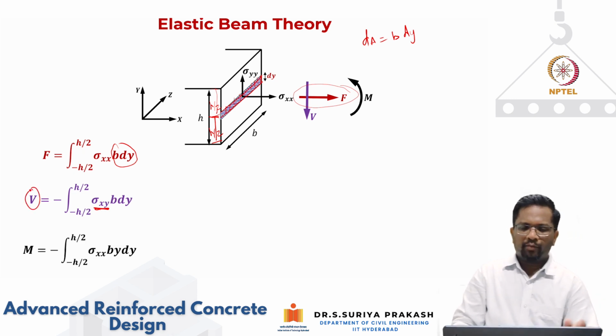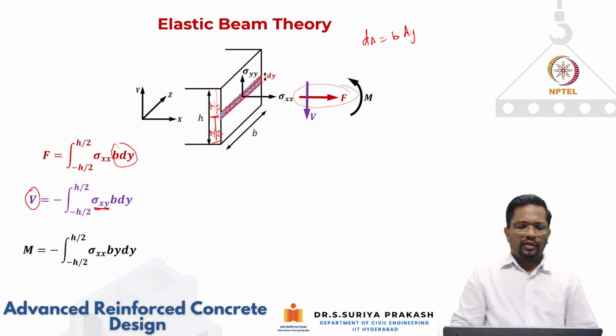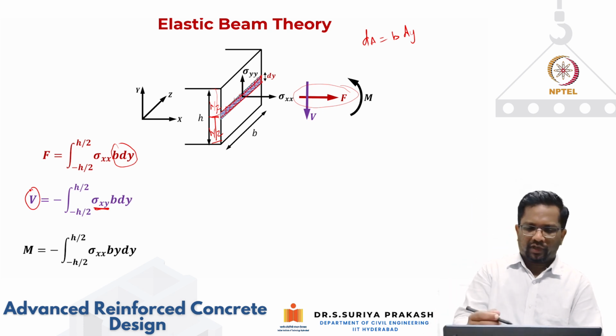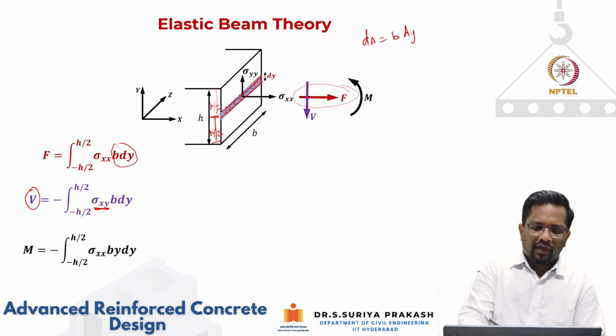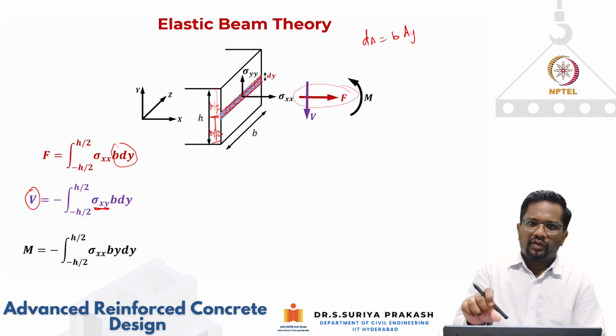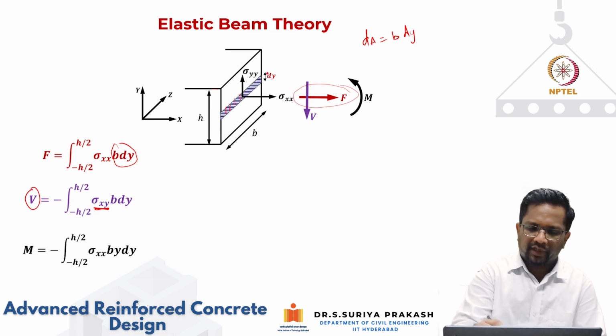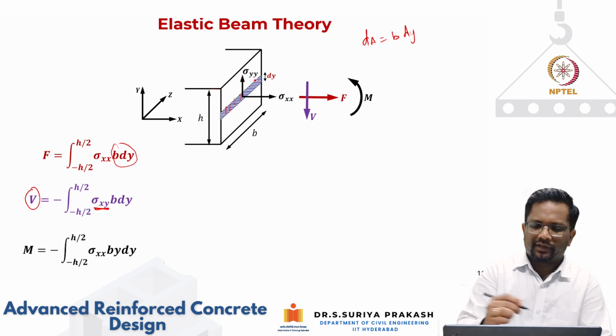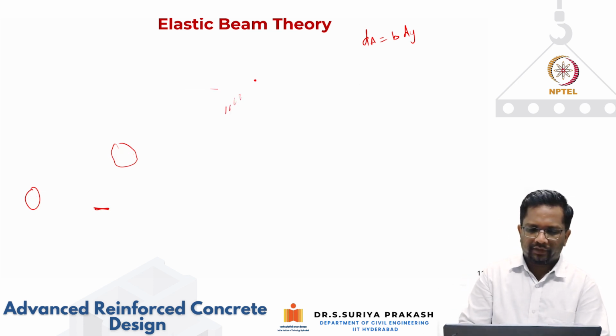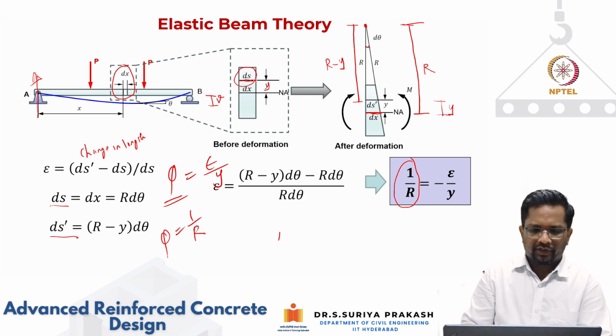Now, what is bending moment? Bending moment is not only about the horizontal force that is acting; I have to take the moment of that force about the neutral axis. This small element, dy, is taken at a distance of y from the neutral axis, like what we have seen here. So if you see here, we have taken it at a distance of y.